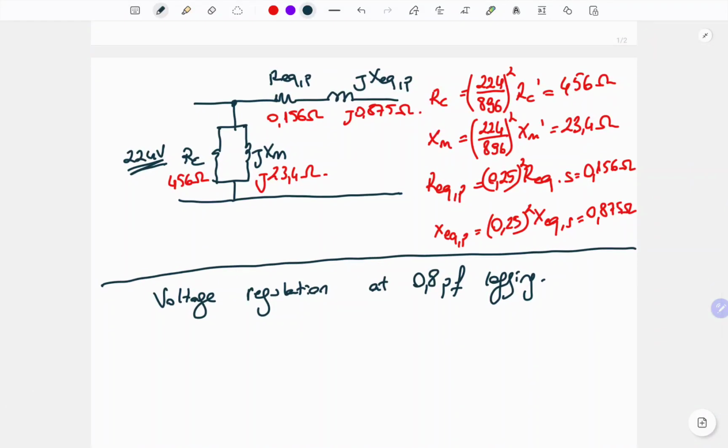So for the voltage regulation, we need secondary side full load and no load values. And as we discussed previously, no load secondary side voltage means Vp over A, which represents the primary referred to the secondary side, and which includes the losses, voltage drops, in addition to the secondary side rated voltage.